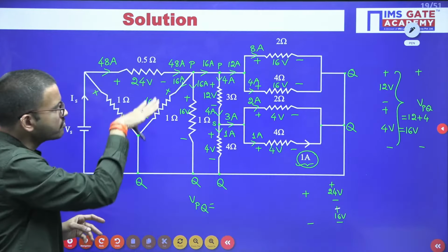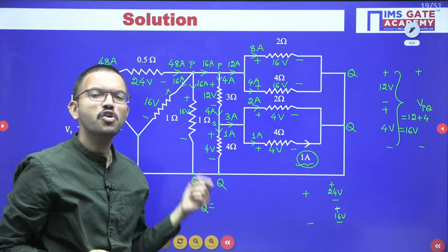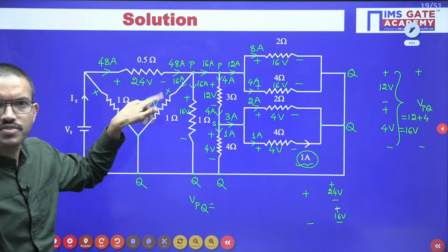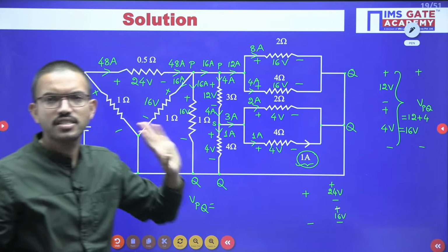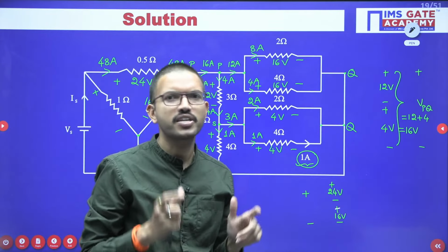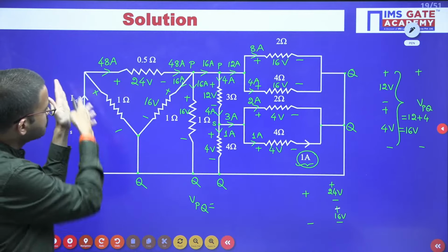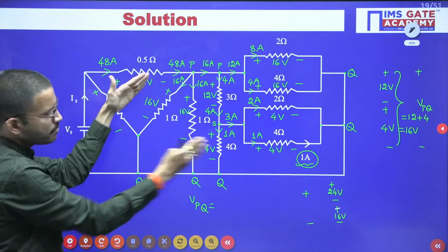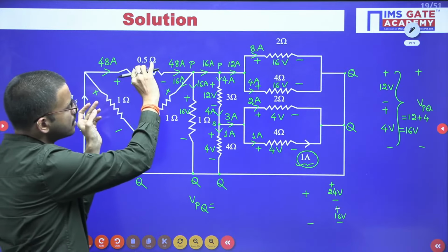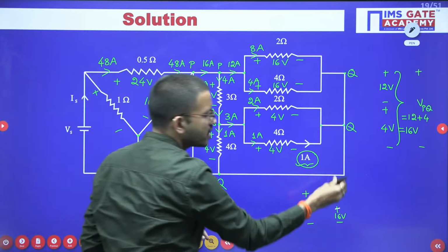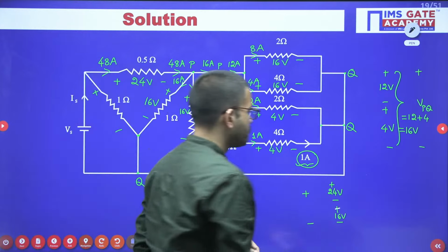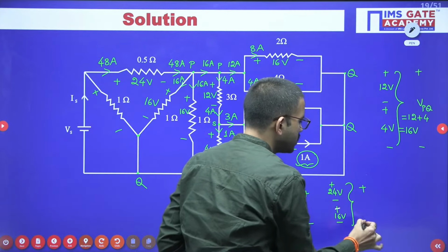Of course, with the help of KVL only you will get the same answer, but without writing KVL, how easily we can find the unknown voltage in a closed path. Whenever you know the voltage across the remaining branches, how easily we can do the calculation, whether addition operation or subtraction operation, right? So here plus minus polarities are there. These two elements I kept vertical. First I have considered this one, 16 volt, and then the moment you have kept this resistor like this, voltage polarities are getting plus minus, and both are having the same polarities. Yes, very good, Manoj.